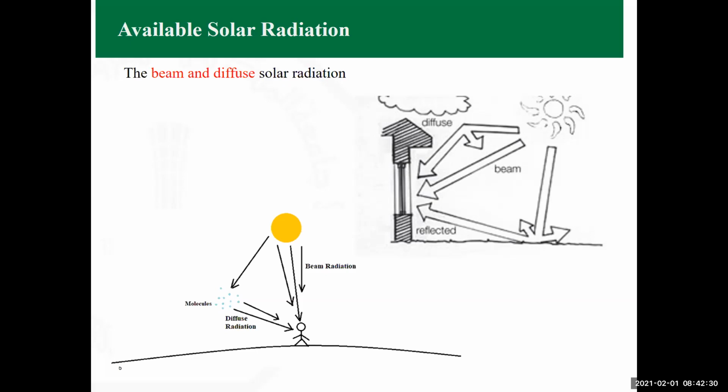On the other hand, PV panels rely mostly on beam radiation. However, when we are talking about heating processes, what we are looking for is both diffuse and beam radiation. Although it might be cloudy and the PV panels would receive less energy directly coming from the sun, the solar collectors that use heat receive higher values because they receive both diffuse and direct or beam radiation.